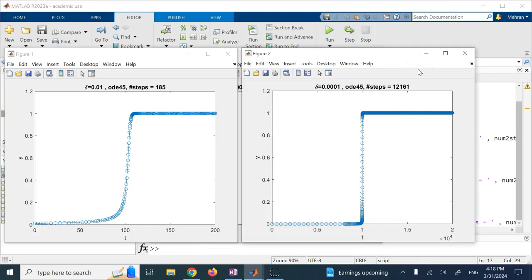Okay? And you might say, well, the simulation time is bigger. True, but the behavior of the curve has not. It's still this kind of sigmoid curve, and there is no reason for this region to have all those samples because the behavior is the same. So ideally, even if I increase this simulation time, it should have handled it instead of 180 with something like, I don't know, 500, 400, something like that, not 12,000. That is too much increment, okay? And this is not really something super acceptable.